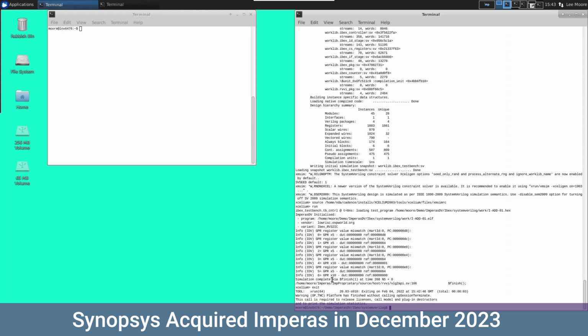in X10. Now, the first thing I would mention about this is that unfortunately we don't really have a lot of information here regarding the flow of execution that led up to this point where we saw the difference, and this is now where we start to get into the details of how we extract more information whenever we get problems with the state comparison between the RTL DUT and the ImperasDV environment.